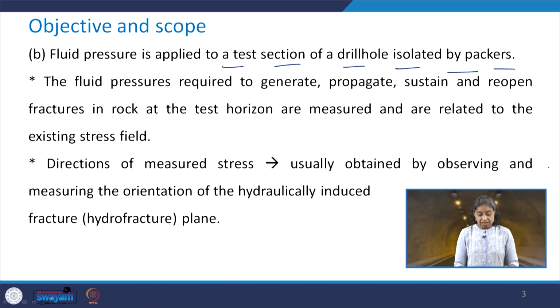Along with this, the direction of the measured stress is usually obtained by observing and measuring the orientation of the hydraulically induced fracture, which we call the hydrofracture plane.